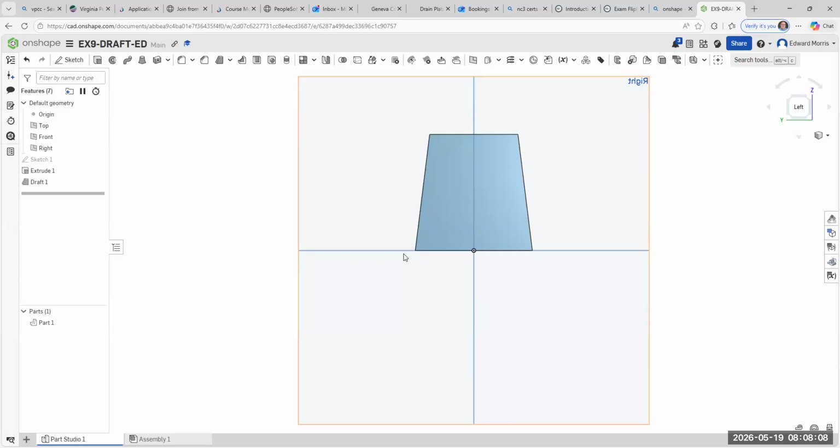Okay, you understand what I'm saying by the cup? Next time you go home, look at a cup, a plastic cup. Look at the sides. They have a slight angle to them. That's called the draft angle. And what happens when they're manufacturing these cups, the die where they form it has a slight angle there. Otherwise, if you make it perfectly vertical, guess what? It may not come out of the mold very easily or the die. You see what I'm saying? Yes or no? Okay.